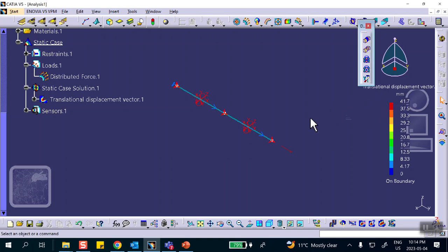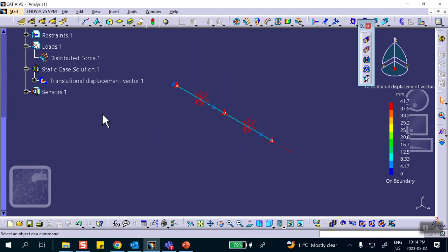Okay, so it is correct. Good, but I do need this load here, because later on when I do free vibration, I have to drop this force to 0. I have to move this thing by 1 millimeter, or thousandths of a meter, and this is going to go with it, because I'm going to do it very slowly and then drop it. It's going to become free vibration. Okay, so far so good.